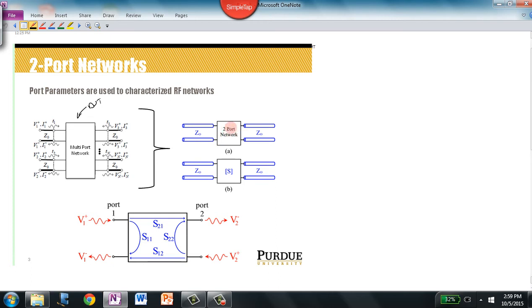So for those nonlinear devices, the two-port network based on measurement is very handy. A lot of times at high frequencies, our conception of voltage and current actually doesn't apply anymore. However, certain port parameters do, and we can easily measure them with lab equipment, even at high frequencies. Port parameters can be combined together in cascade to build more complex systems.